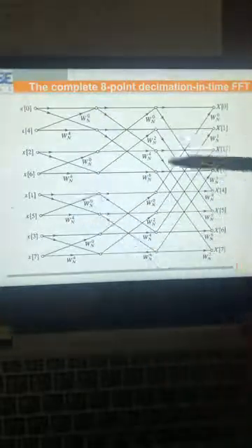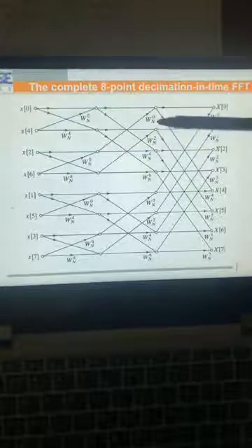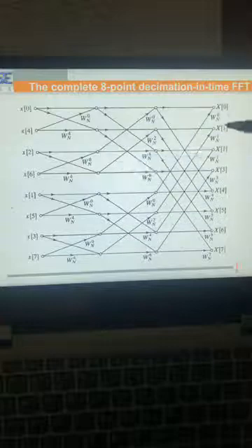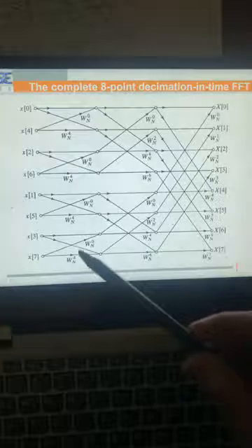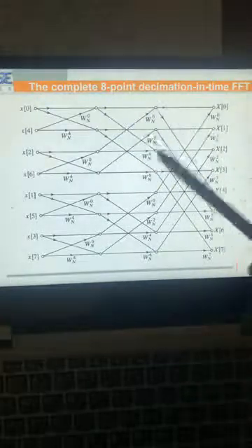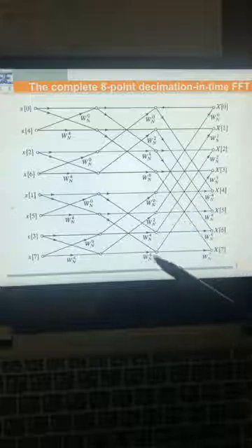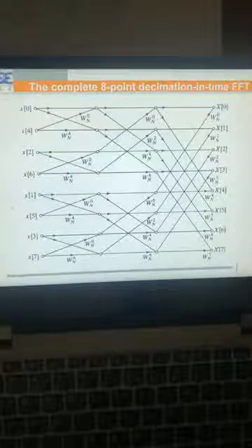And remember, I told you that you can have the same twiddle factors instead of N by 2 or N by 4, and you just scale it accordingly so that you don't have to recompute these factors. So you do 2, 2, 2, 2, then you combine these two together, so you get these 4 points, then you combine these. Every stage would have N by 2 butterflies. Remember, these are 1, 2, 3, 4 butterflies.